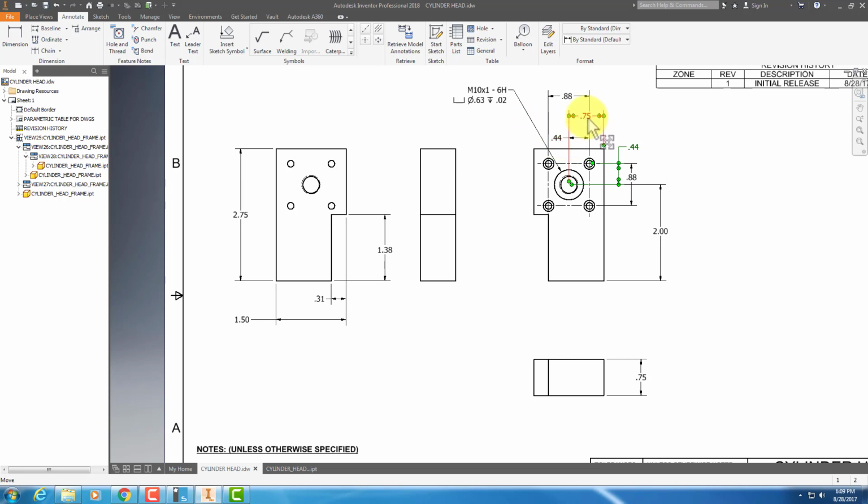And notice how if you pull a dimension, is this correct? This is our dimension line. We cannot have anything running through a dimension line. So the trick to that is bring the dimension right over the extension line and it'll make a break. Tricky, tricky. Like this one. And that would be okay. All right, so we have those holes right there.